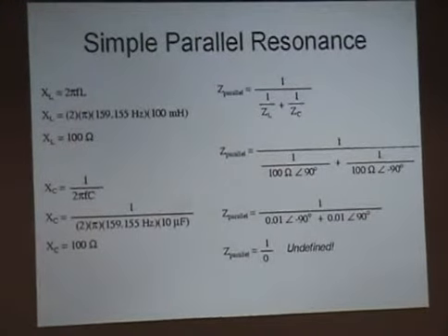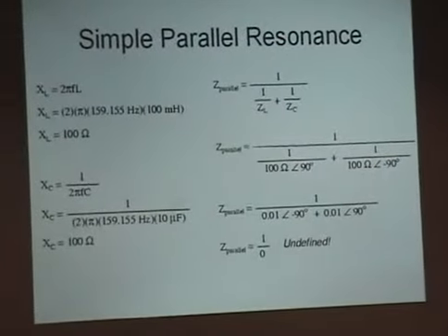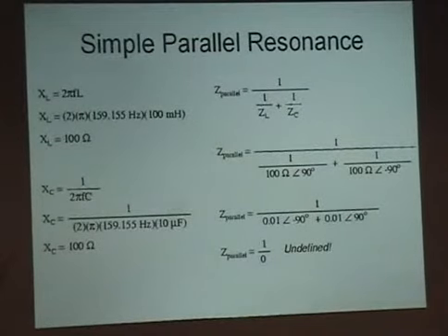Parallel resonant tank, if you're talking about looking into it, no, this is the impedance. This is the impedance in there, and the impedance goes to 0 in the tank. The current would go to infinity. But outside circuitry, looking at a parallel resonant tank, you're not going to see the same thing. No. This is inside. This is kind of a magical thing that happens at resonance inside.